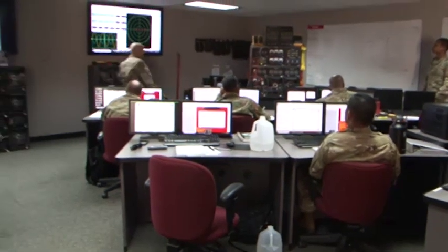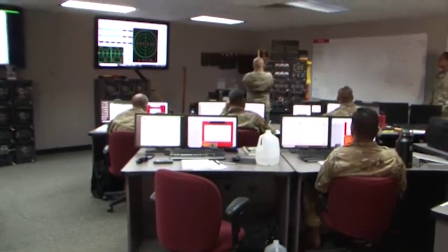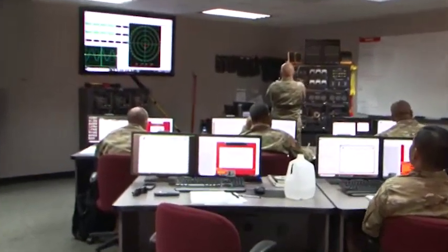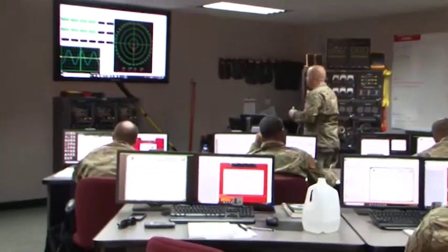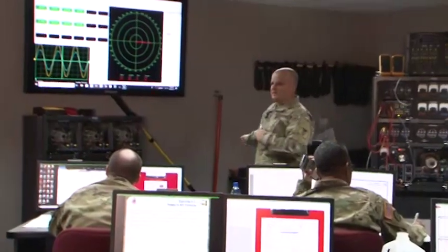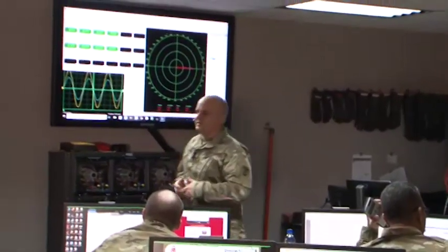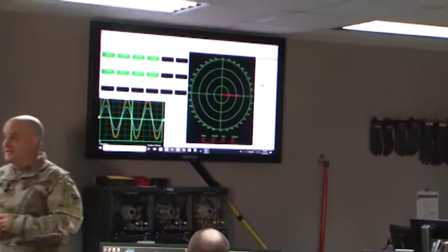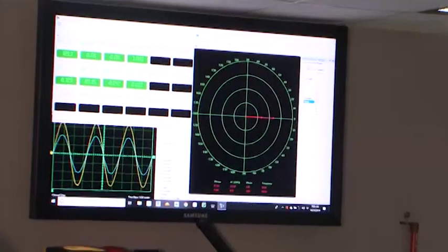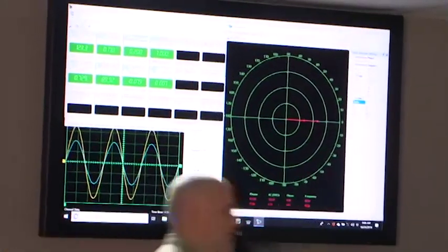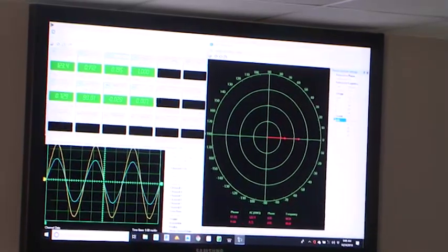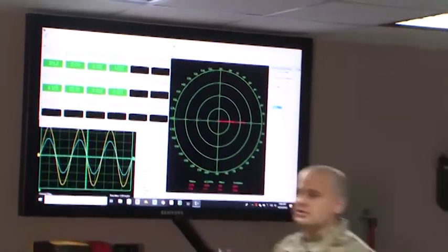What do I got here? Let's see which one is out of phase. Now, how did I know that was off? Because they were opposite. They were what? 180 degrees out of phase. But how? I mean, we know that resistance should be in phase, right? You had your voltmeter backwards. Yeah. So I just visually looked, just from understanding the circuit, and realized something was wrong, right? See that? Okay. That's why sometimes looking at the oscilloscopes, looking at these diagrams, you can deduce things if you understand a system. You wouldn't know anything about that if you didn't think into the system.